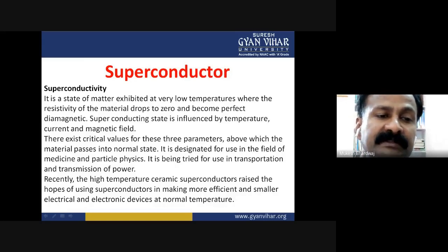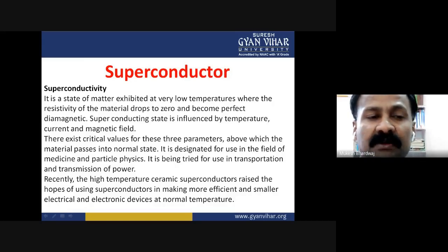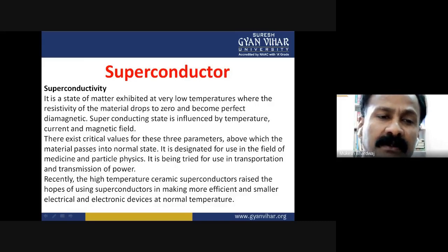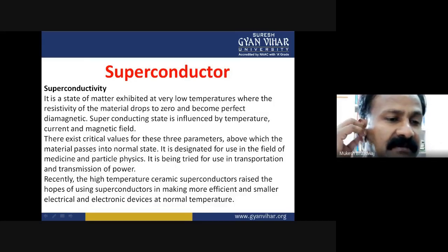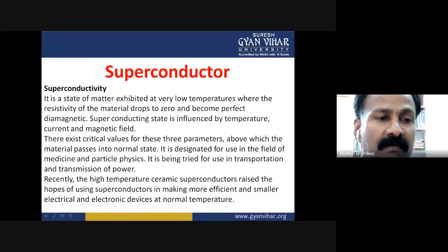Elemental germanium and silicon are obtained by chemical deposition of compounds such as germanium oxide, silicon chloride, and silicon hydrochloride. Once the semiconductor material has been isolated and preliminary purification steps have been performed, it is melted and cast into ingots. Upon cooling from such a casting process, the silicon and germanium is polycrystalline. The atoms are arranged in diamond lattice over small regions of the ingot.